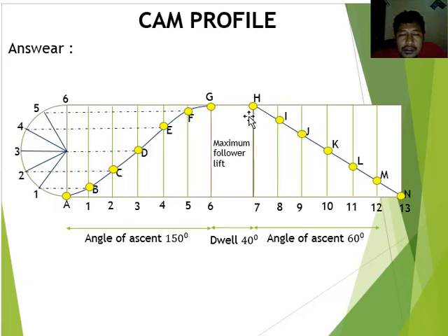Because the fall motion is uniform velocity, the points have the same velocity, and you can draw a linear line like this, between S and the end point. This is the motion for the displacement of the follower.